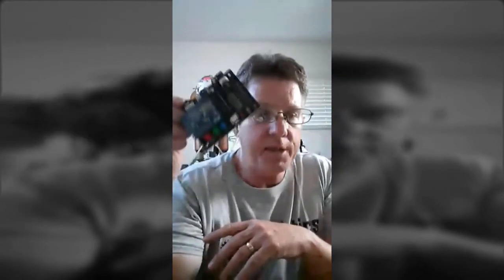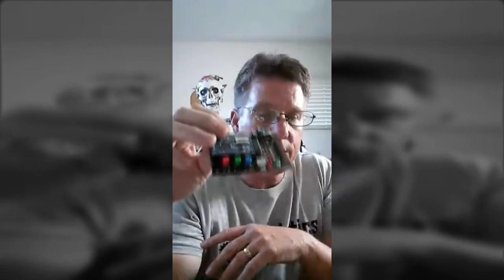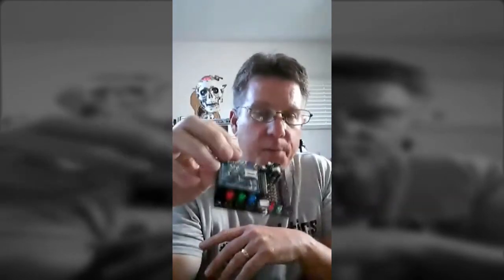It drives my Pickaxe chip, does all the other stuff to drive the board, but the servo power is supplied by a different power supply, which is really nice if I'm setting them up that way, because some servos run 4.8 to 6 volts, and some of the little tougher servos will run 7.4 volts. So I can run a bigger power supply.